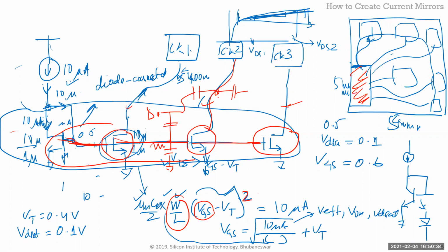So if you have a nice current source with a really large output impedance, which Santanu is going to cover when we do the different types of current sources, you'll see that the error is going to go lower and lower. So that's why you can route a drain signal all the way, and you'll be much less susceptible to noise than taking a gate voltage.